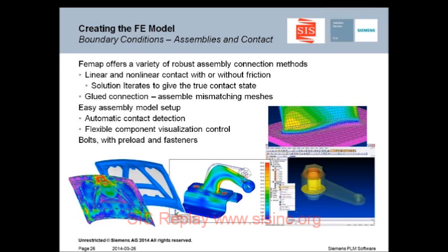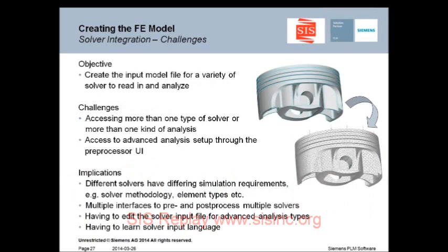As long as the two components share the same plane of connection, then you can do this. And the results are actually very good. It's a good way of connecting dissimilar meshes. You have other things like fastener elements, bolted connections as well, and surface contact, three other images shown on the slide here. So many and various different ways of connecting together assemblies of components, which is more and more required these days.